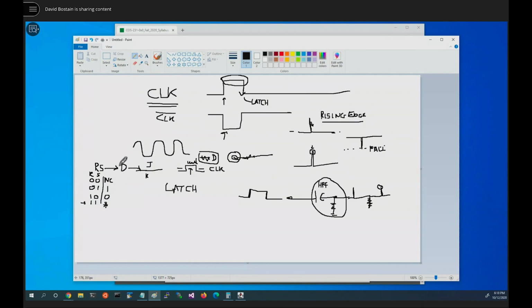So this state is just, you don't allow that. Which is what the engineers took advantage of to create the D flip-flop, because they recognized that unless you need this don't-change state, we can just use these center two values here by tying R and S together, one of them through an inverter, as D, and we can get the two center things to occur. Now, D without a clock, of course, since we don't have this state, is useless. Just adding a normal level clock like this means D can change the entire time it's high, and we call that a transparent D latch.